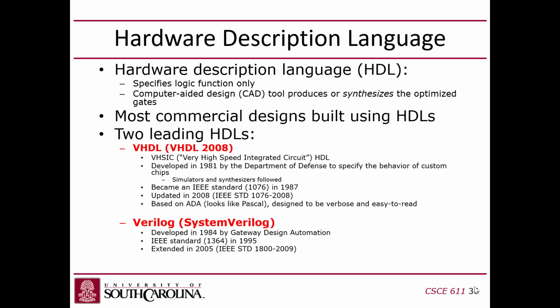So Verilog came out a few years later. VHDL is kind of a government project. Verilog came from industry. Verilog looks closer to C. It's more efficient and it's more sparse, but it's hard to read. So you better comment it, because you can have a little bit of Verilog, but it's not really clear at first glance what it's doing, because it's not all spelled out.